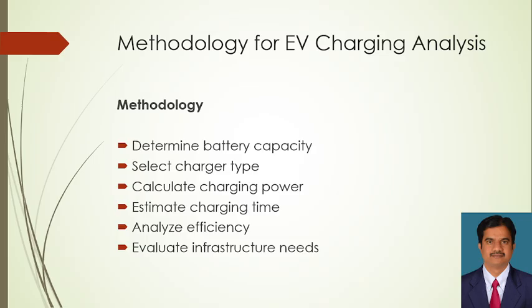Methodology involved in the EV charging analysis. Determine the battery capacity, then select the charger type, calculate charging power, estimate charging time, analyze efficiency, and evaluate infrastructure needs. So first we calculate the capacity of the battery that we have in the electric vehicle. Based upon the capacity, we need to choose whether it is level 1, level 2 or level 3.